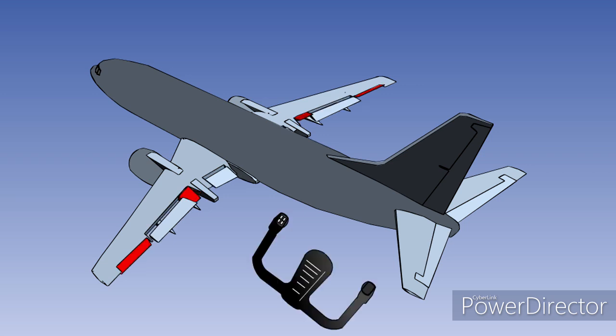On some aircraft, with both inboard and outboard ailerons, both sets are used at low speed. But once the flaps are retracted, the outboard ailerons are locked out and only the inboards operate. On others, the outboard ailerons are used in isolation until the flaps are retracted. The system then switches to the inboards only.